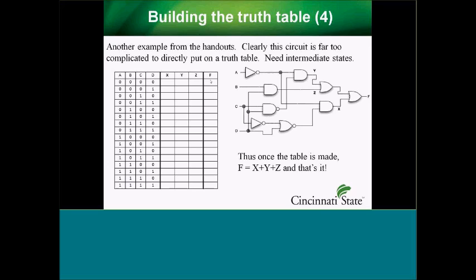It's slow going, and typically with a problem like this, I would have them do the chart, and then there would be 4 or 5 more steps. Then they would take it and, okay, I want you to Boolean reduce it, or I want you to do it with a K-map later on, and then maybe redraw its simplified version with NAND gates or NOR gates or something like this. But this is a very common type of thing.